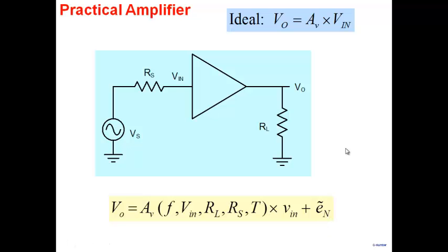When I think of amplifiers, what is important? Well, you may be thinking, if I'm talking about voltage amplifiers, the only thing which is important is how much is the voltage gain? That's not true now. Voltage gain is there, but we have to talk about how your amplifier behaves with respect to frequency. How does your amplifier behave with respect to the magnitude of the input voltage? How does it behave with respect to RL and RS? How much noise is there?